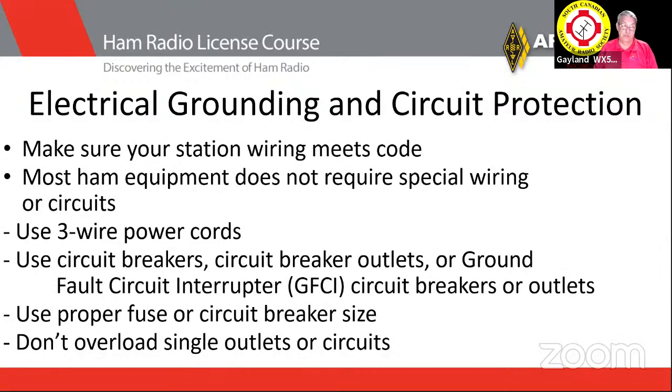Can you imagine? And there were 2 sets of these. So can you imagine the power load of 8 or 9 repeaters, or even 6, which would be the number of outlets in a normal power strip? I can assure you it's more than the 15 amp circuit breaker that was in the power strip.